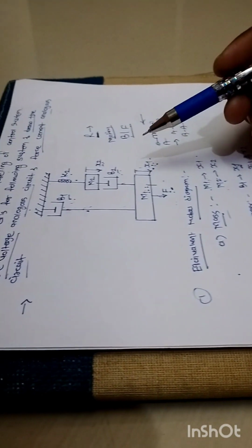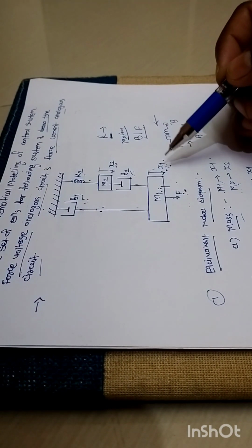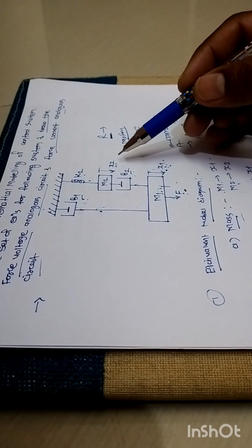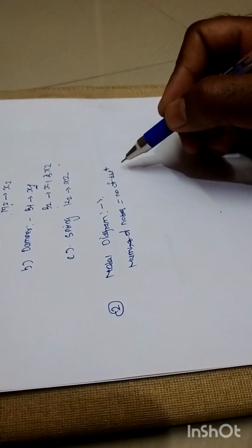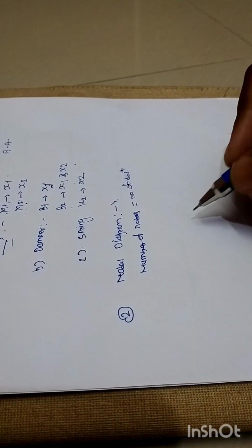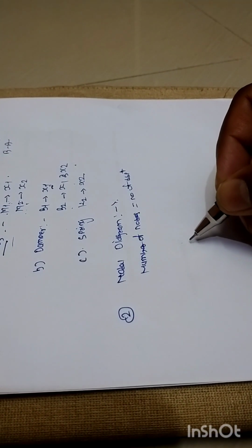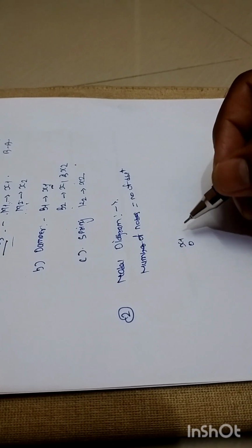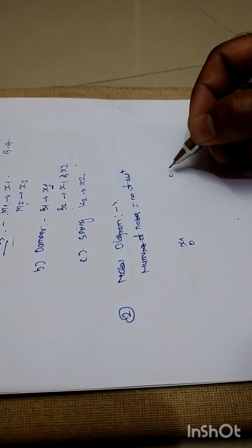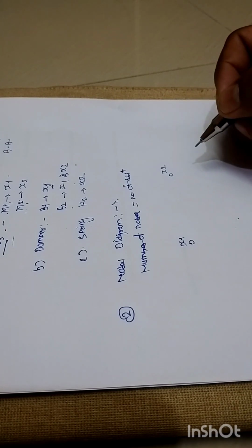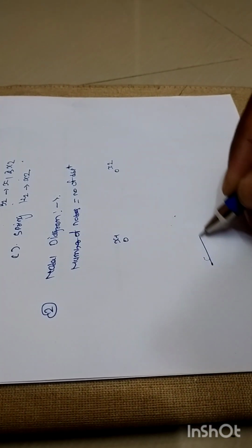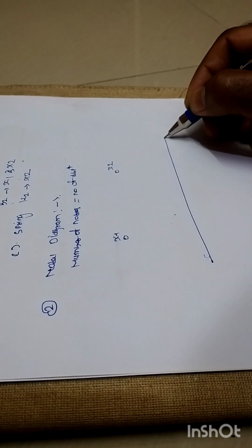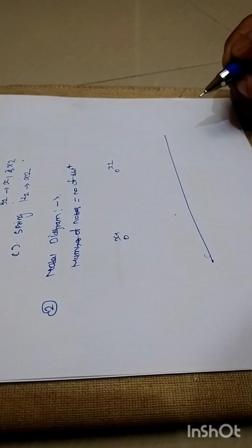As you can see, there are two: displacement number 1 and displacement number 2. So we need to include two different nodes. This is the first node associated with x1 and this is the second node associated with x2, right? And this lower line represents the ground surface or the ground axis, right?